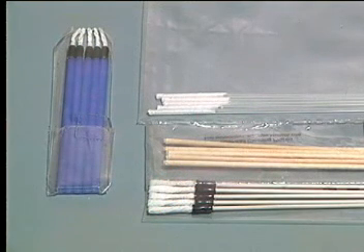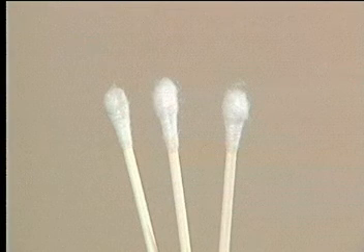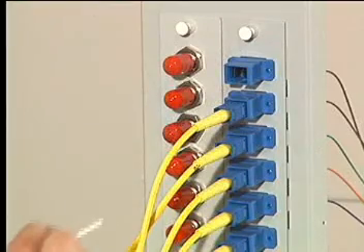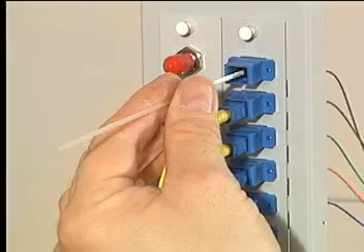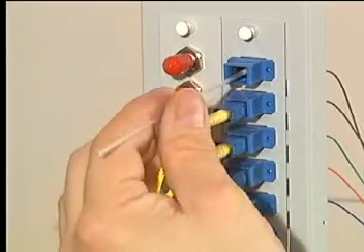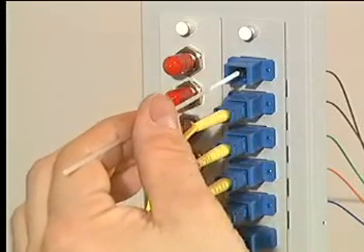These swabs are available from a number of manufacturers and are selected to match the ferrule diameter of the connector, such as 2.5 or 1.25 millimeters. They are manufactured with materials that will not contaminate the connector. Never use store-brand cotton swabs, as they contain excessive lint which makes them undesirable. The swab is inserted in the sleeve while rotating clockwise and pushed completely through the sleeve. Between 4 and 6 rotations of the swab should be completed before the swab exits the sleeve.